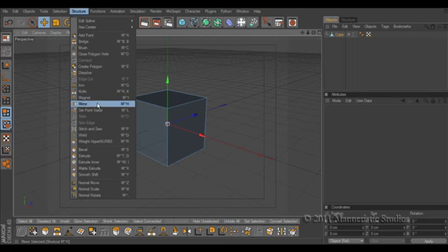We can pull out the surface using the magnet tool. We can work as we're modeling on one side of an object, and we can mirror it to make a symmetry and a complete object. We can set point values. We can stitch and sew, meaning that we can stitch up areas that have 5-sided or 3-sided polygons, and we can make those into 4, and we can sew them back together, somewhat like the weld, which we'll talk about next, but it's sewing together to make it more even inside of the mesh.